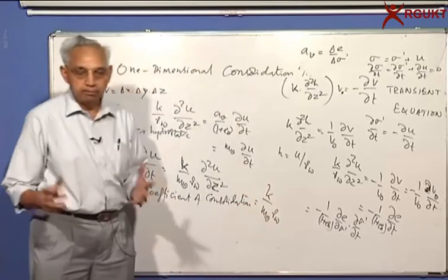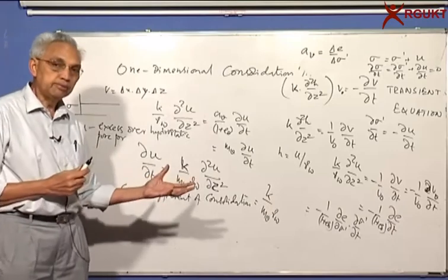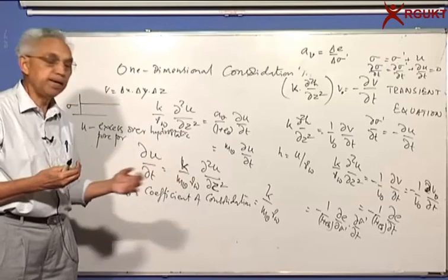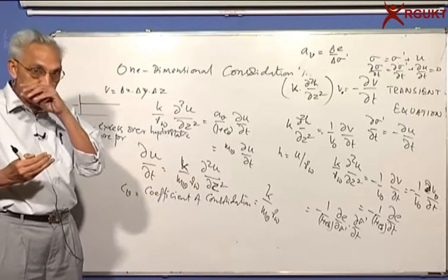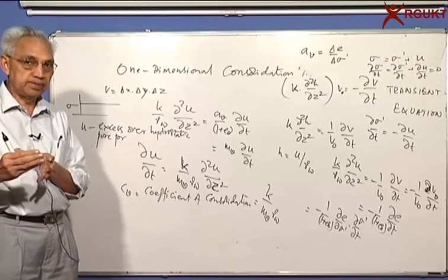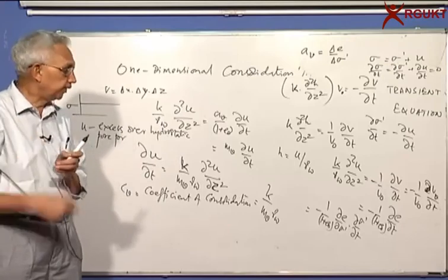So unlike in most metals, in soils the hydraulic characteristics and the mechanical ones are coupled. So consolidation is a coupled mechanical problem of deformation as a function of time. Why does it become a function of time? Because the water has to escape.